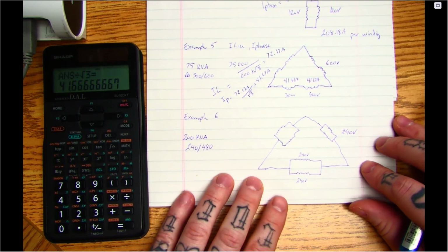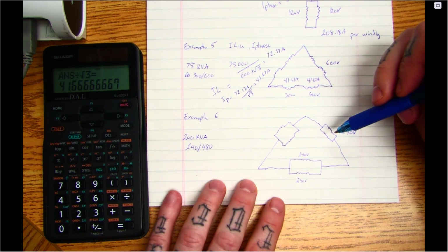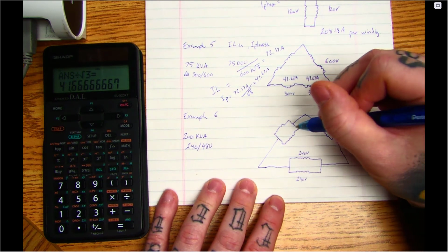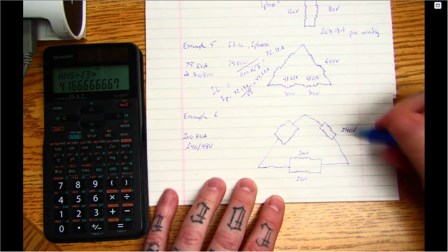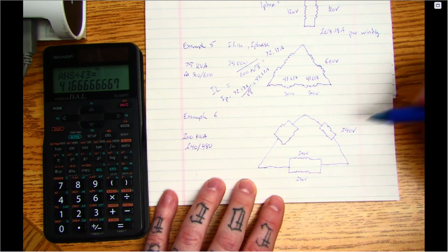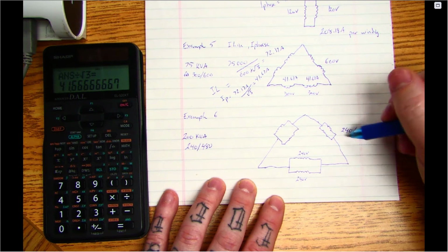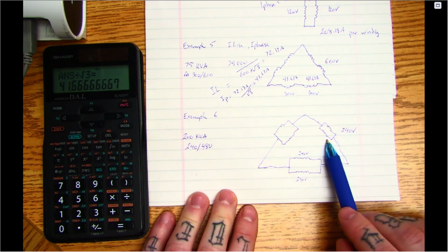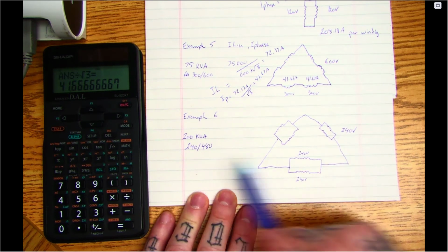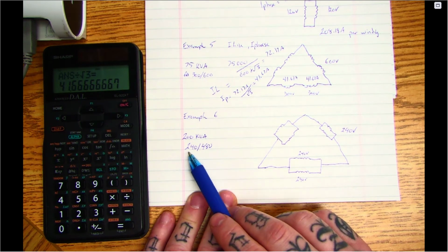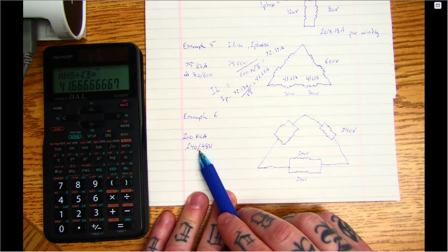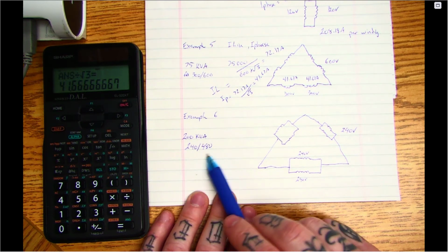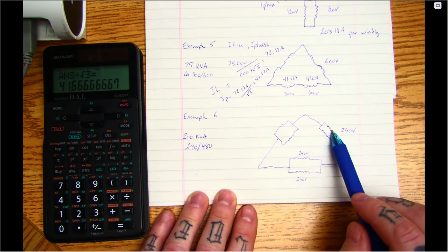Okay, the last one here, I think that's the last one we got from the module. So this is the same kind of deal. Forgive my rudimentary drawings here. We're going to have these windings hooked in parallel. This is right out of your module, that's where these voltages and values are coming from. So now they're saying on a phase level I got 240. That shows me that's my lower voltage connection, because if they were connected in series, I'd get the 480. So that 240/480 is telling me that I have a dual voltage alternator that I could hook up for either. In this case we've hooked it up for the low voltage because they're in parallel.